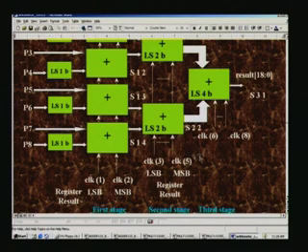Therefore we do not really bother about extra additional pipelines. The higher the pipelining you do, the higher will be the throughput, that is, the speed of operation will be much higher. That is a desirable thing, and of course you have to pay a price of additional pipeline registers, and that will be only a marginal increase. So you are free to use as many pipelines as possible.